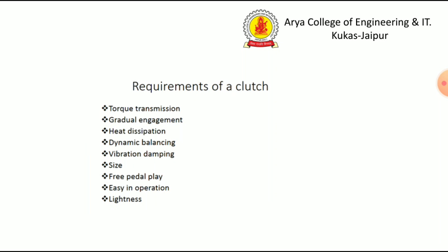The basic requirements of a clutch: torque transmission, having gradual engagement, high heat dissipation, dynamically balanced, vibration damping, small in size, having free pedal play, easy to operate, and light in weight.